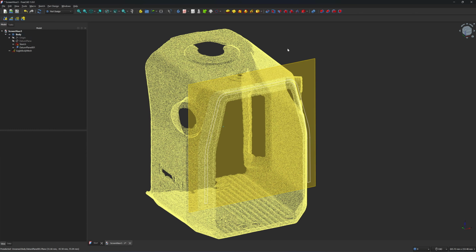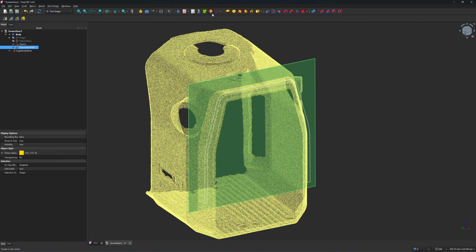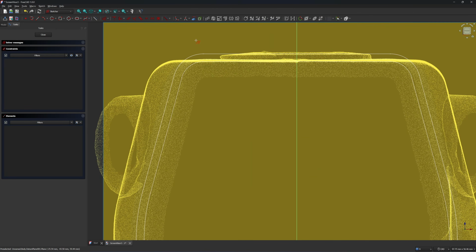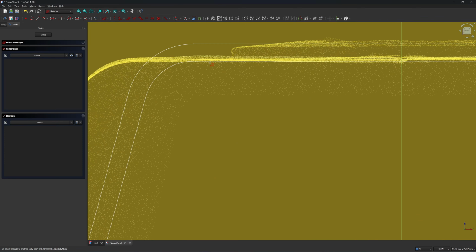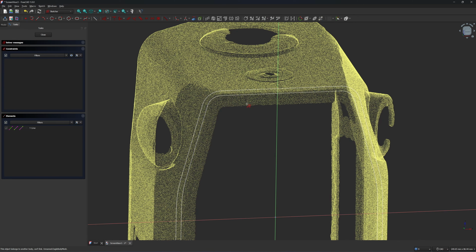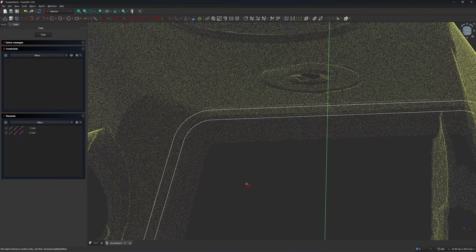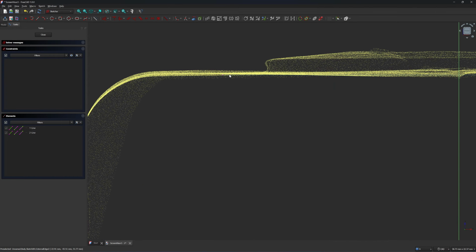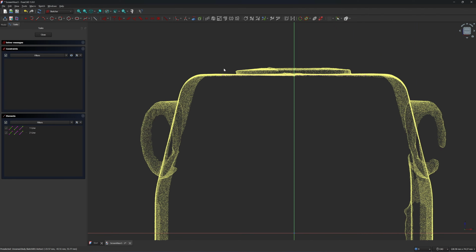Next, I'm going to create a new sketch. Click on this plane, create a sketch. I'm going to project the geometry from the first sketch, which is this one, and create external reference. Okay, so it's quite difficult to click sometimes. This is the projected line. You probably can see it.